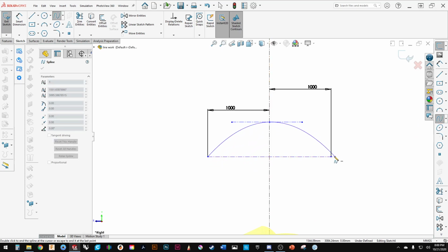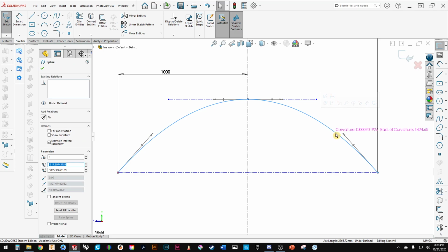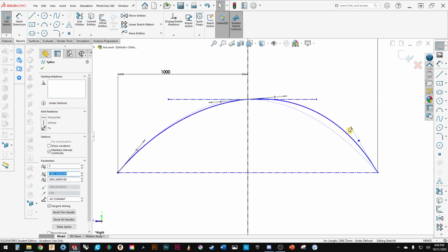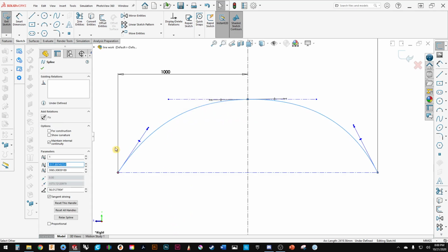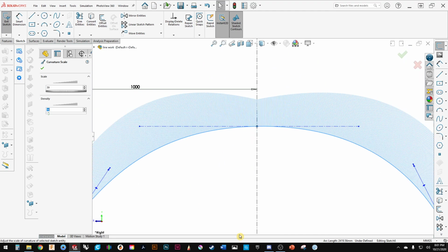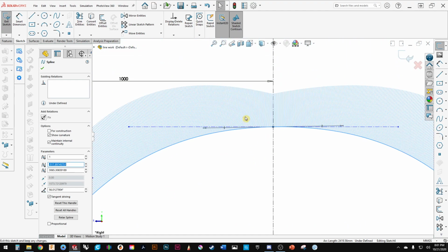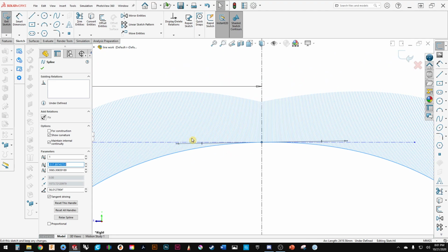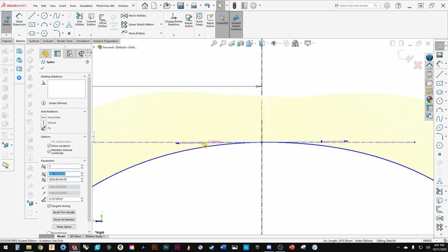So here you see now that I'm controlling things a little bit better, but it's not going to be a perfect arc, and I'm never going to get it there. And you can see that splines are hard to manage, so if I'm trying to get that perfect arc, it's going to be difficult. It's just the way things are. You can see here I've got a bump now. Well, how am I going to fix that? Well, I've got a bump in it because this is angled at that point. So if I come in and I edit this, it's not perfectly smooth at the top.